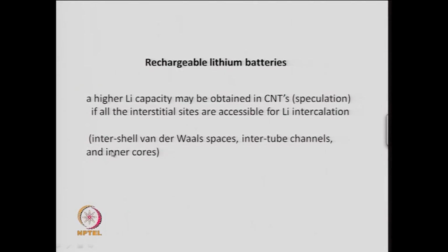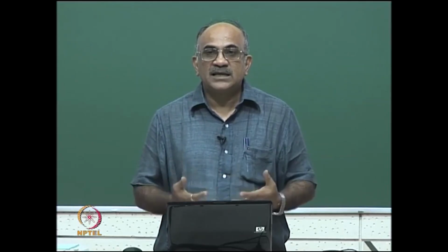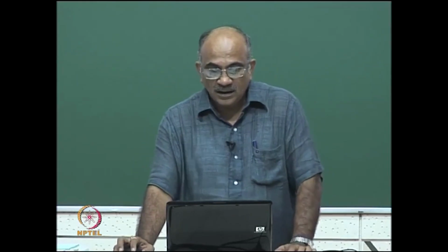And here the intershell van der Waals spaces, the intertube channels and inner cores are the places where the lithium can be intercalated. So, there are several spaces where lithium can intercalate into the carbon nanotube, and a lot of possibilities are there for enhancing the lithium capacity. Now, depending on how much lithium you can take in or take out will result in how many electrons per gram you can recycle, and that will lead to a very high capacity of the batteries.